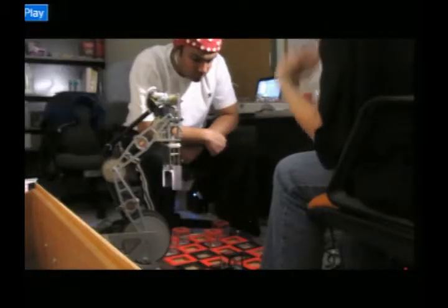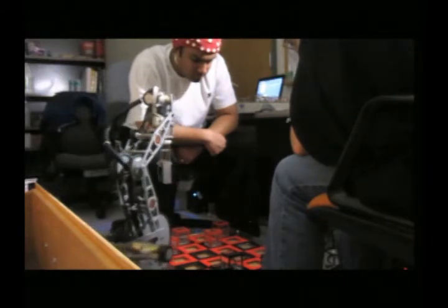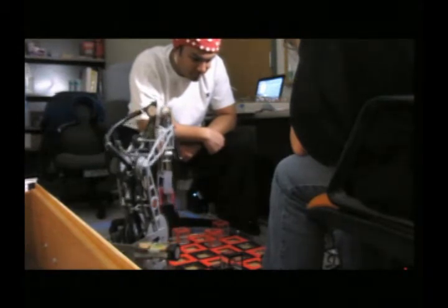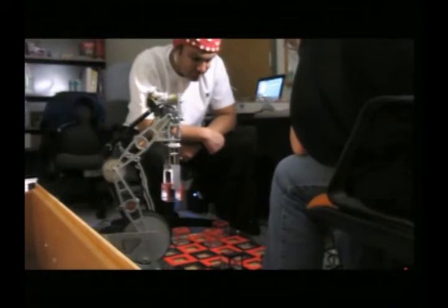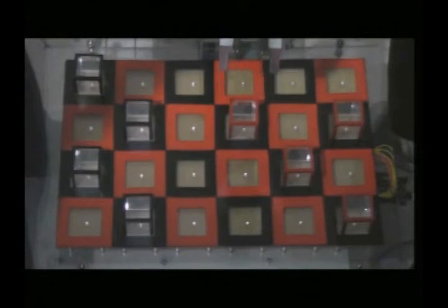Before we get into the results of this thing, let's actually see how this worked in action. All right, so this was the robot coming up from its calibration position. You can see that these 2 LEDs are flickering right here, and then after 2 seconds, the classifier starts and you pick the 13 hertz signal, which is right here, just from my gaze on that particular square. There's only one move, so it moves directly from there.